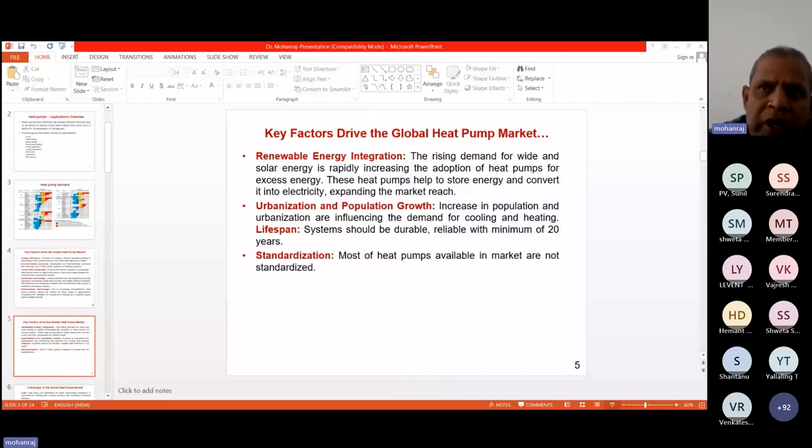So it is very essential to identify some energy efficient and environmentally friendly working fluids. Recently the olefins have been introduced to meet the requirements for heat pumps, with a low global warming potential of around 4 or 5. It has been introduced as an option to replace the existing R134A, but the problem is that this olefin has a major problem of fast decomposition, and it will form trifluoroacetic acid. TFA is the major problem with R1234YF or R1233ZE.